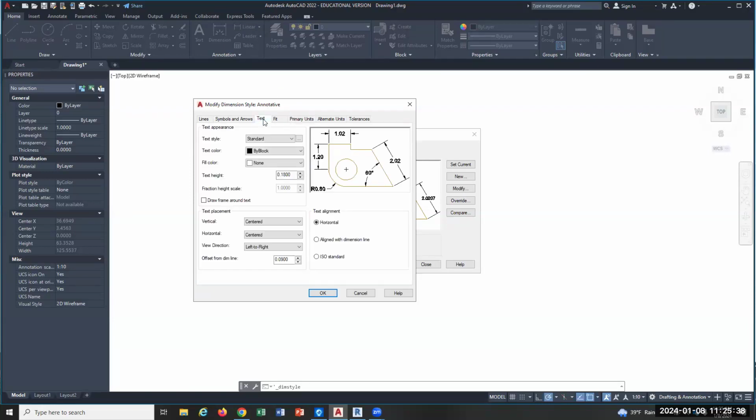That's good. And then in text, I want my text height to be whatever the customer wants, and I'm the customer, and I want 1/8 of an inch, 0.125, right? Those are the primary things you have to set. Your precision and the text type. Then you set it to exactly what you want, and then AutoCAD will do the whole scaling thing for you.